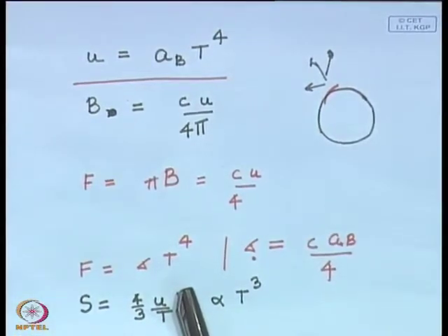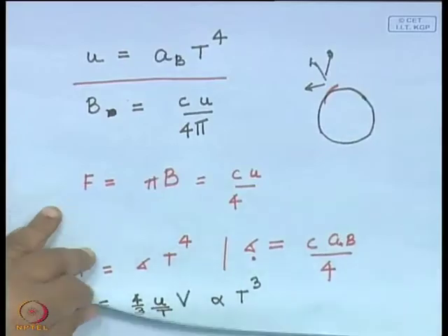Okay. So, what have we done till now? Let me briefly recapitulate before we move on to more detailed discussion. Until now we have first defined what is thermal radiation, what is black body radiation, and then we determined certain properties of the black body radiation. Its specific intensity is a function of temperature alone, it is isotropic.